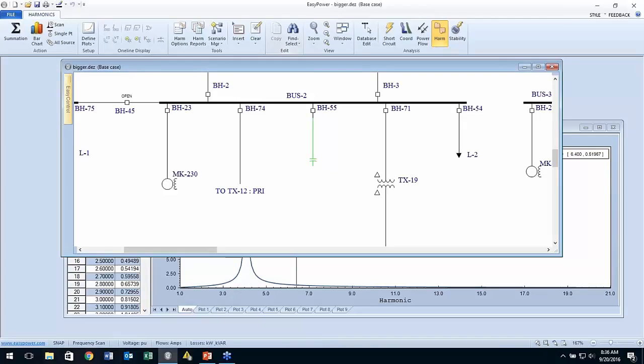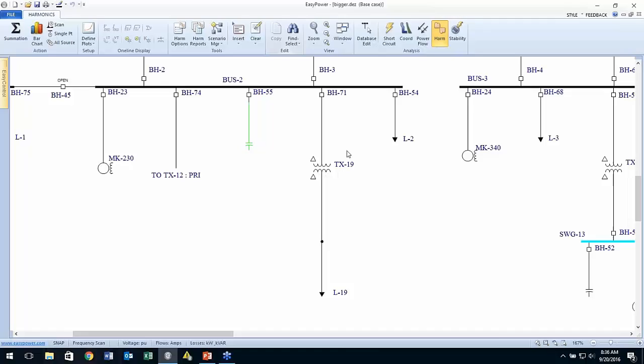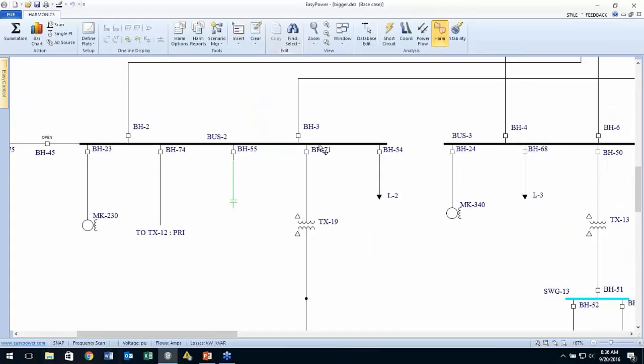Okay, so did we do any good? The point I'm trying to make is that there's value in the database that was collected when we were doing the ARC study, and the more accurate that system is, the accuracy of the system can actually be developed utilizing power flow by taking regular readings, and this I would encourage your customer to do themselves, to take regular voltage and current readings at specific times on a periodic basis and compare those with what the power flow projections are for each bus.